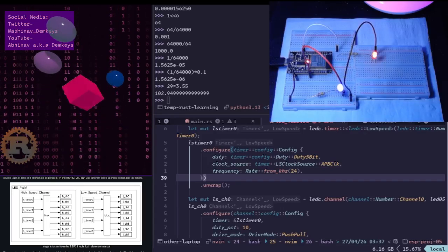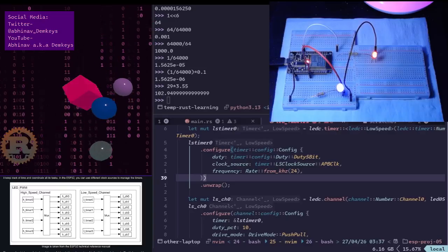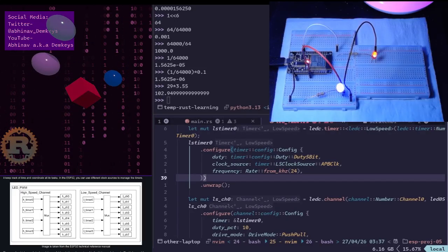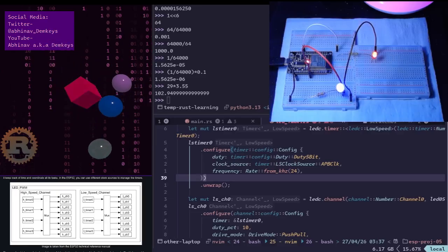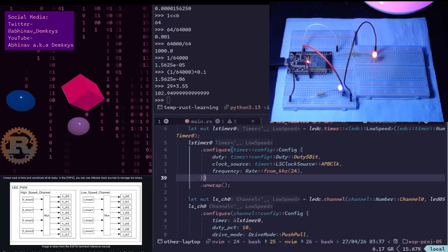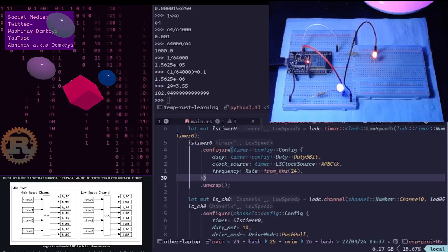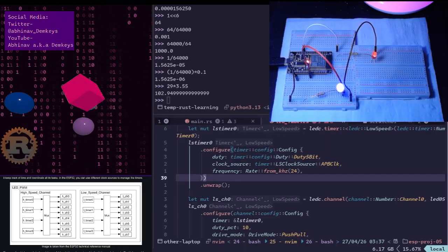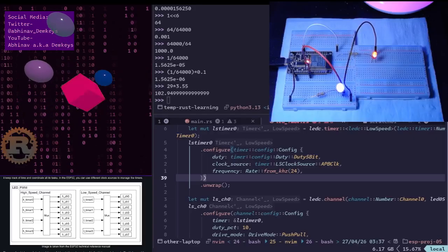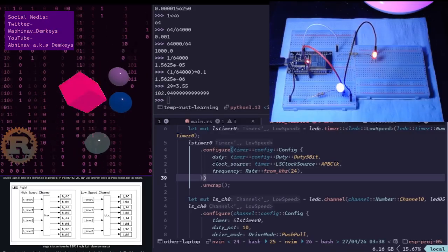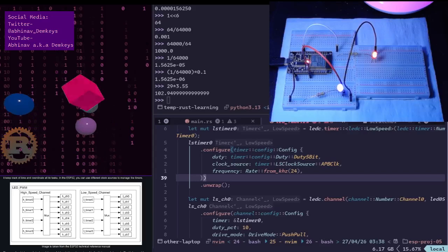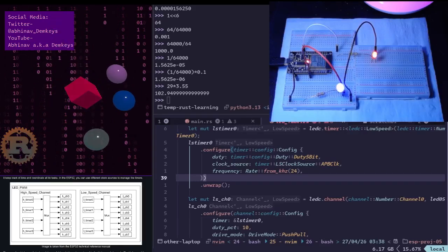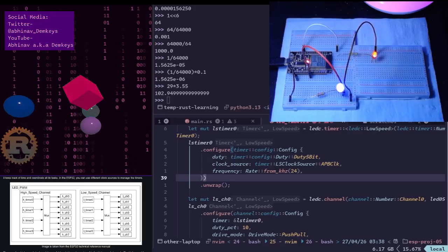So PWM, the LEDC peripheral. Then we have something called the ultra low power coprocessor. Wait, let's read the LEDC PWM. As you discovered, the LEDC, or LED control peripheral, has its own internal timer. Once the CPU tells it, flash this pin at 500 Hertz with a 50% duty cycle, the hardware handles the timing. Even if the CPU goes into light sleep, the hardware clock continues to pulse that pin.